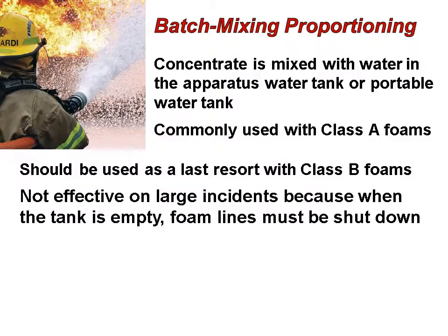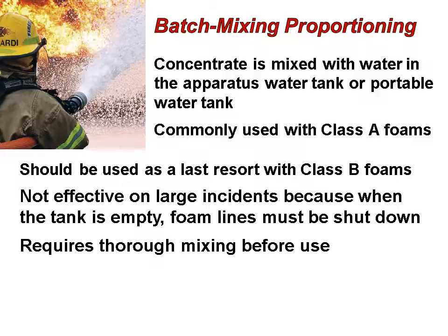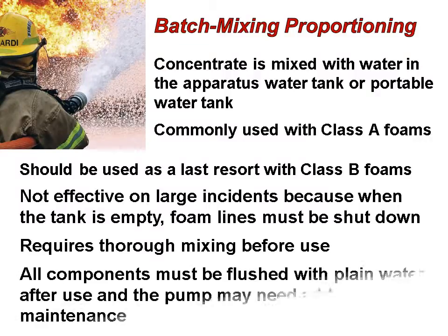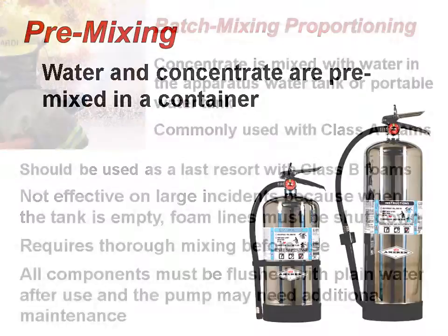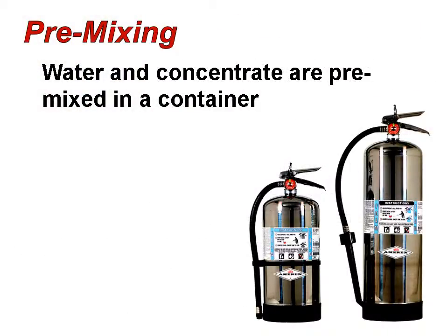It's not effective in large incidents because when a tank is empty, foam lines must be shut down, and then the foam starts to break down in the line. It requires thorough mixing before use. Then all components must be flushed with plain water after use, and the pump may need additional maintenance to make sure you get all the foam out of there, so you don't damage any of your equipment.